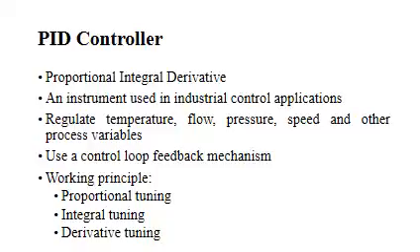Then, integral tuning. This attempts to remedy this by effectively calculating the error result from the previous action to increase the correction factor. For example, if the oven remained below temperature, I would act to increase the heat level delivered. However, rather than stopping heating when the target is reached, I attempts to drive the cumulative error to zero, resulting in an overshoot.